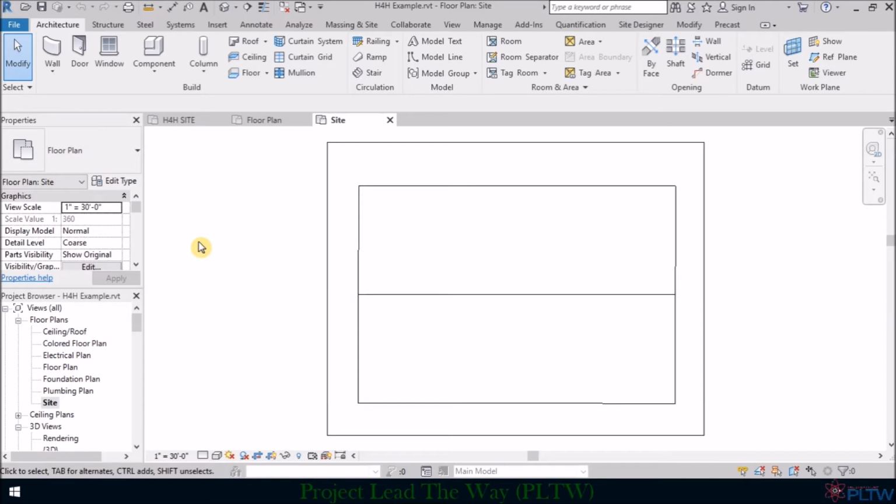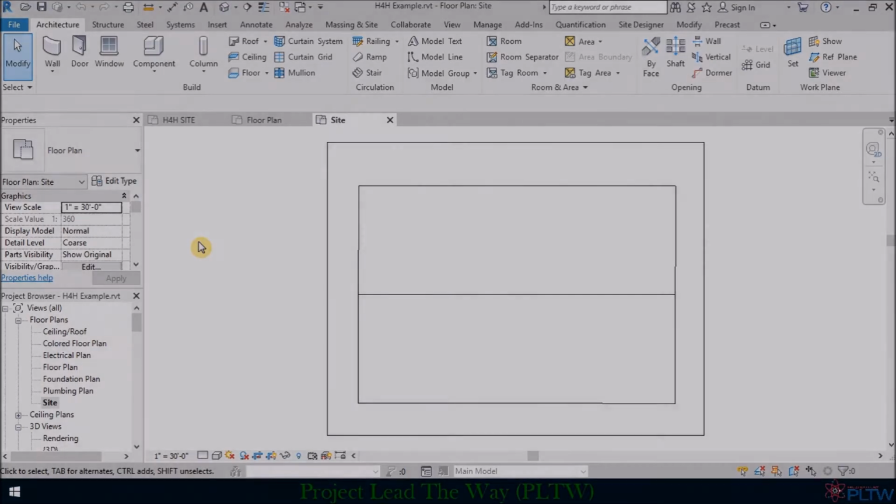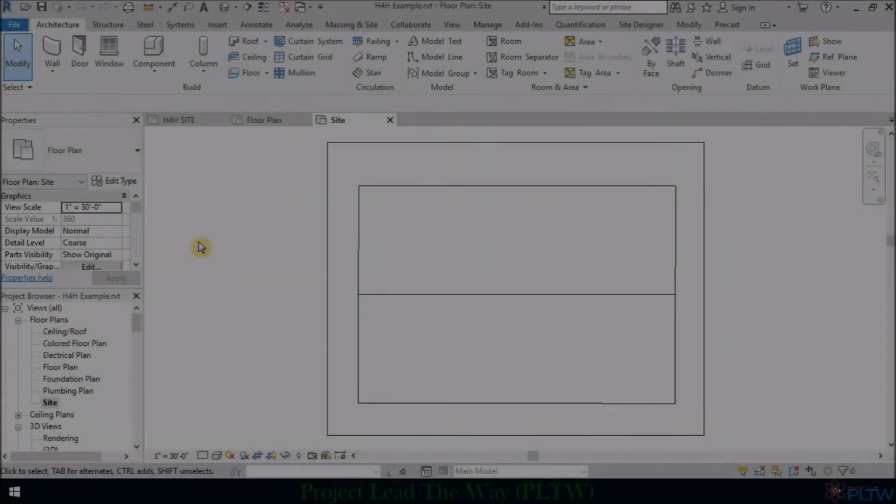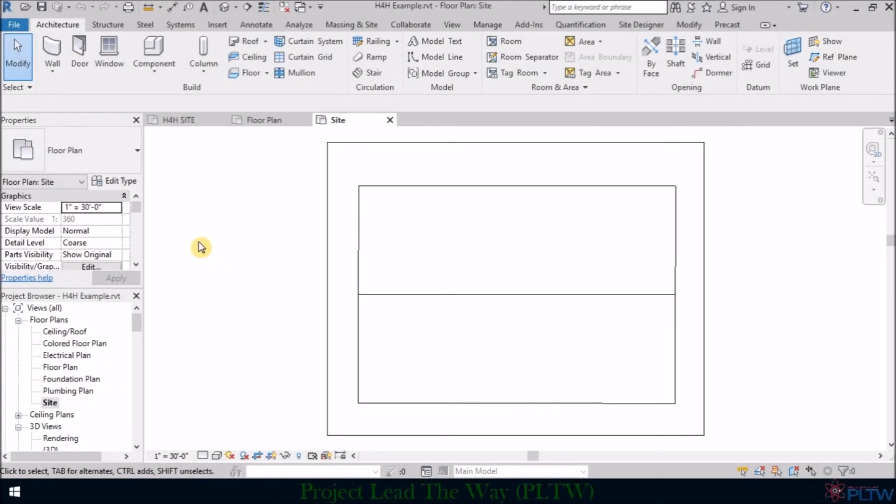If you do, we will need to hide those items after it has been linked or inserted into your site plan Revit file. Your file must be saved with this view visible. Once everything looks good, save your file. Then close your Habitat for Humanity design Revit file and make sure it has been completely closed.